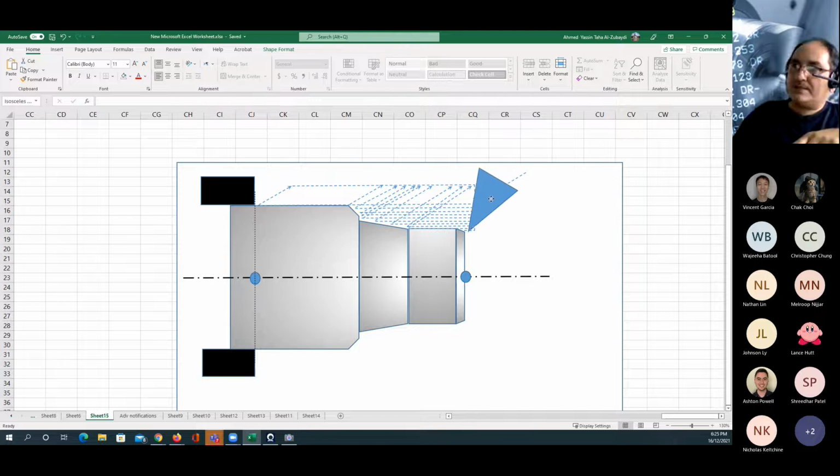okay, after we're doing the last cut here, we can simply go up. Then we go down all the way down to here. Set a depth of the cut of 0.25 millimeter. That's for the finishing. Increase the RPM and move the cutting tool slowly to finalize the cut. Up, chamfer down, and then leave the part and turn off the code.